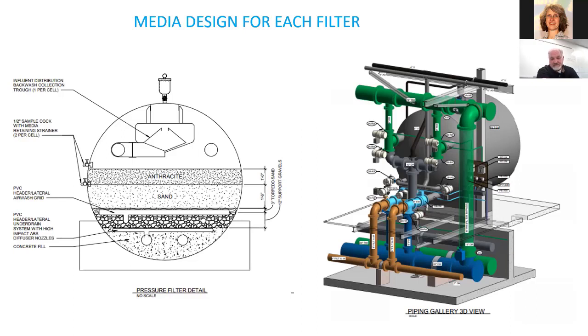Thank you. So we have another question: why do some of the buildings only soften the hot water? Cost. The hot water is only softened because there's nobody living in the building, number one, and number two, when you heat our quality water, the calcium drops out in the hot water heater and shortens the life of the hot water heater.